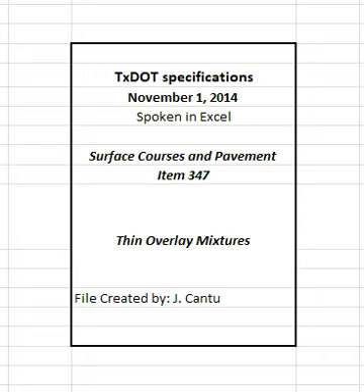See table in specifications. 1. Surface aggregate classification of A is required unless otherwise shown on the plans. 2. Used to estimate the magnesium sulfate soundness loss in accordance with Section 347.2.1.1.2, Micro-Deval abrasion. 3. Only applies to crushed gravel. 4. Aggregates, without mineral filler or additives, combined as used in the job mix formula, JMF.